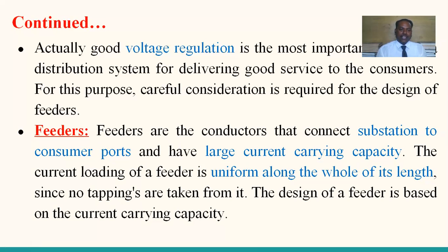Why? Because the nominal voltage is 11 kV. This voltage is not at all suitable for the consumers. So therefore, no tappings on this feeder. The design of feeder is based on current carrying capacity.